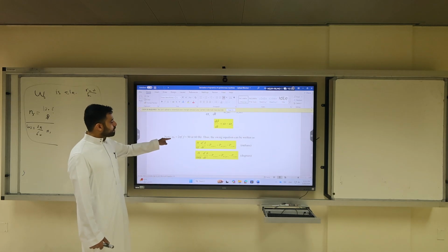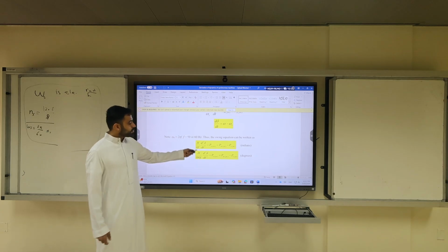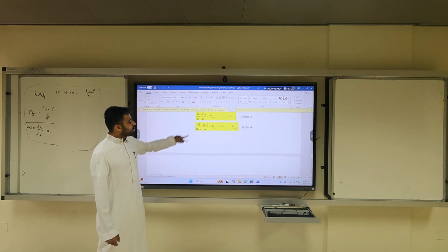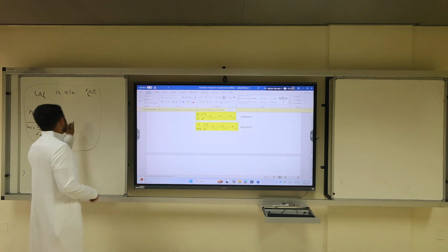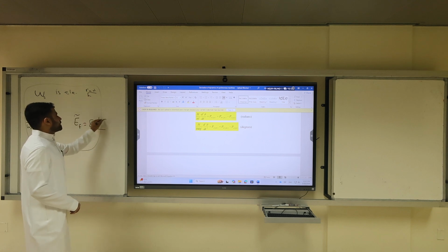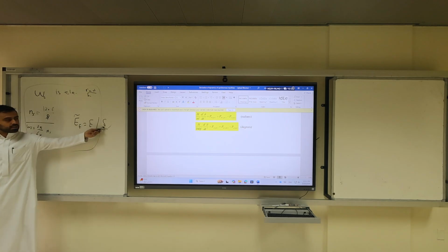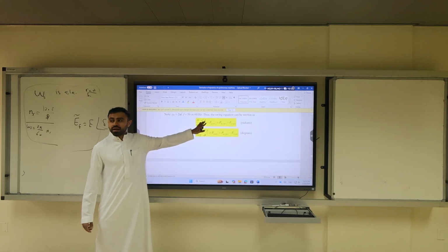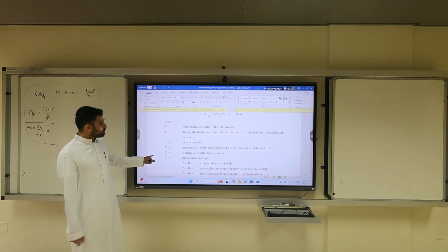Now you can write omega_s is 2 pi f, where f is 50 or 60 hertz. Then you can substitute, instead of d omega, you have d delta, where delta is, you remember, E_f equals E_f angle delta. It's this delta. It's the phasor, so this is an electrical quantity. So we have everything as electrical. What is the delta before?